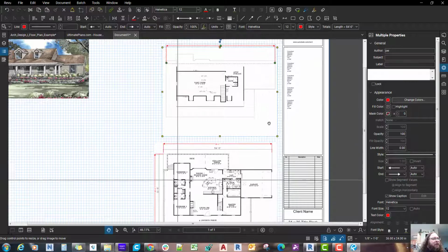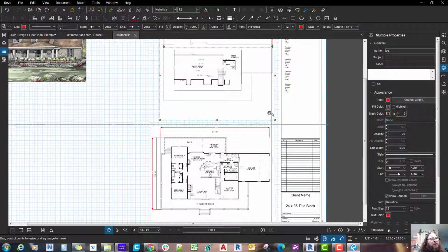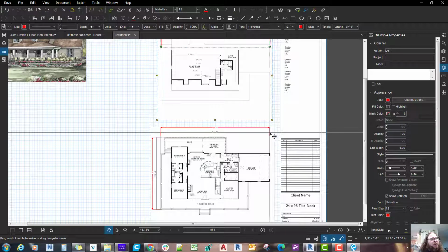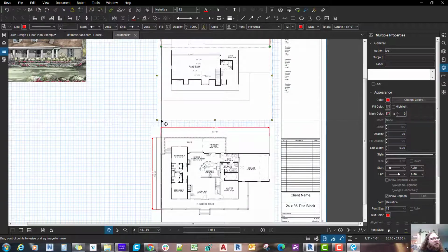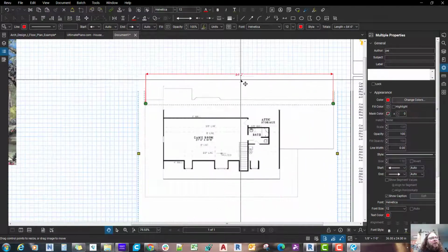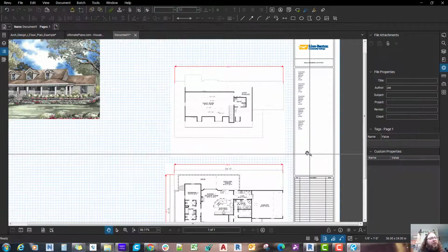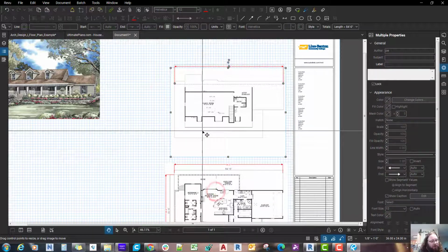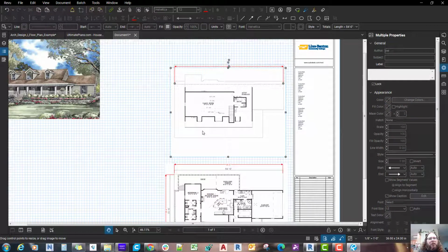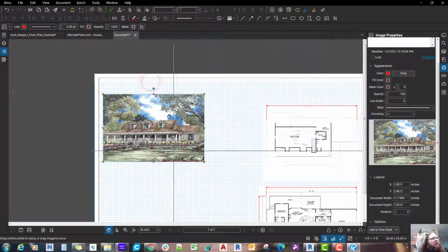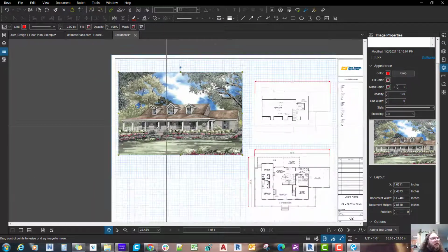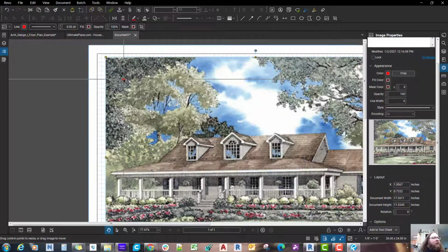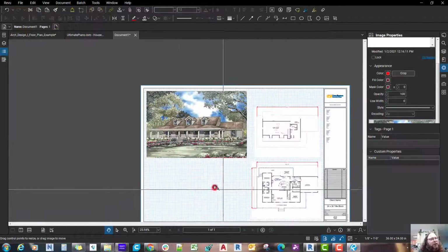And then we'll line it up, because it should be pretty close to what they have here. So yeah, it looks like it's pretty close. So we're going to call that good. We'll hold Shift down, highlight over all of this, right click, and lock. Or you can press Control Shift L, which will toggle through locked and unlocked. And as you see, when they're locked, you can no longer adjust any of their appearances over here. So now we have a reference to start drawing our layout, our floor plan, in Revit.